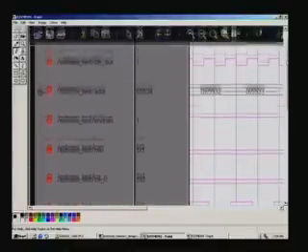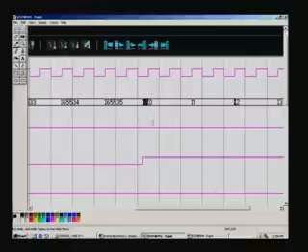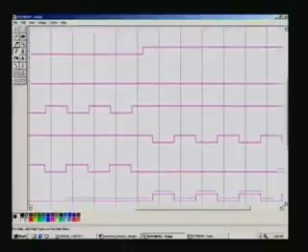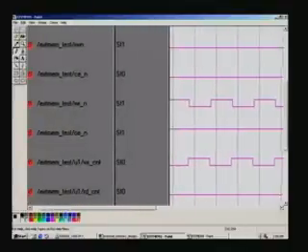So, you can see the clock out and address here, and switching over to 65535 and you can see that RWN changing to read here, it was write here, and that is RW1. Then chip enable is always low, it is at the bottom of this. So, if it is high, it would be on the top of this. So, you can see here it is on the top.